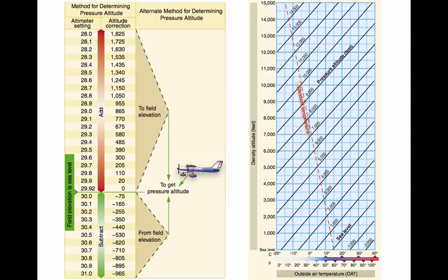Density altitude is used in calculating aircraft performance. Density altitude is determined by first finding pressure altitude and then correcting this altitude for non-standard temperature variations. Since density varies directly with pressure and inversely with temperature, a given pressure altitude may exist for a wide range of temperature by allowing the density to vary. However, a known density occurs for any one temperature and pressure altitude.